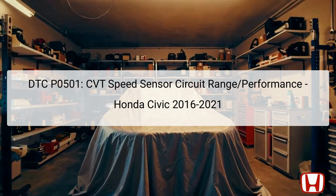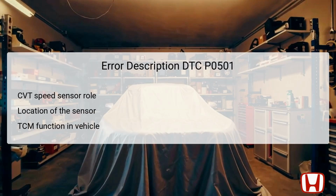The P0501 error arises specifically from electrical circuit problems, not mechanical failures in the transmission system. Therefore, it's essential to focus on electrical connections and sensor functionality during troubleshooting. The CVT speed sensor is located within the transmission assembly and plays a key role in determining the vehicle's speed. It ensures the vehicle's TCM can adjust the transmission settings for optimal engine performance and fuel efficiency.